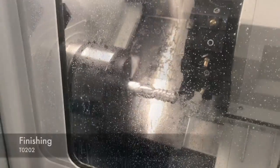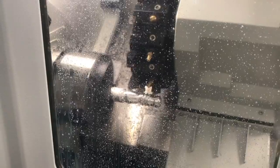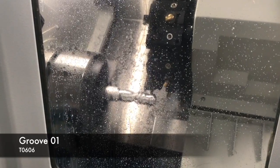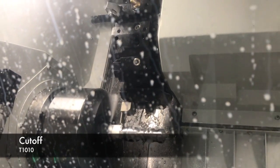Then it calls the T0202 tool insert, which is a 55-degree diamond. Then for the grooving process, it uses the T0606 tool insert, which is a square shape. Finally, for the cutoff process, it calls the T1010 insert tool, which is also square. And you can see how it moves more slowly due to the peck cycle that is set up in the software.